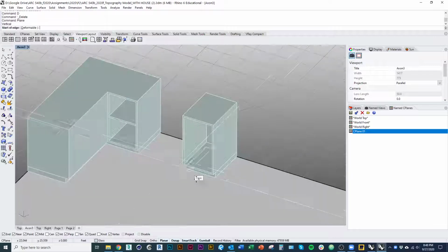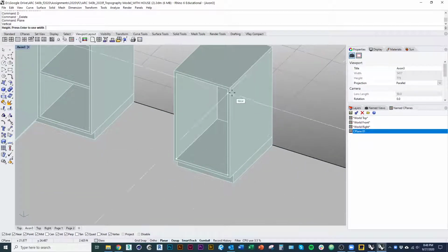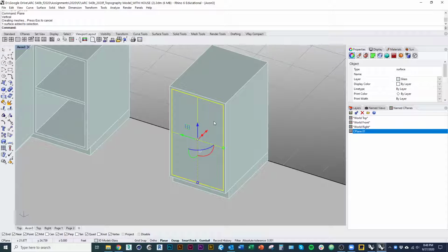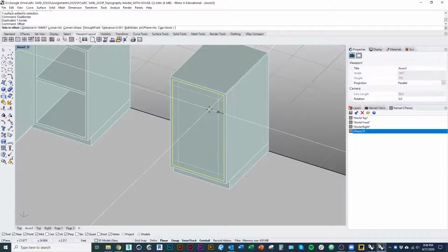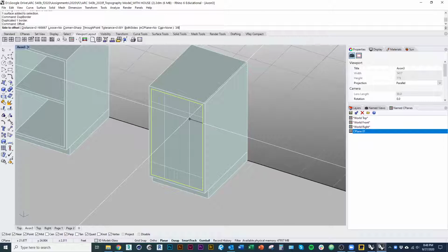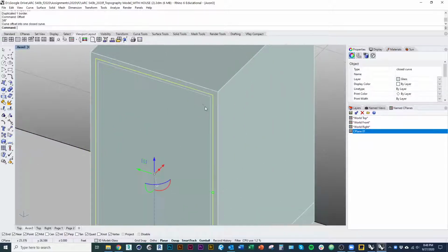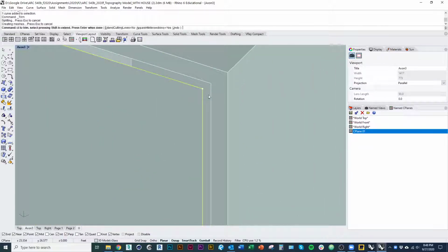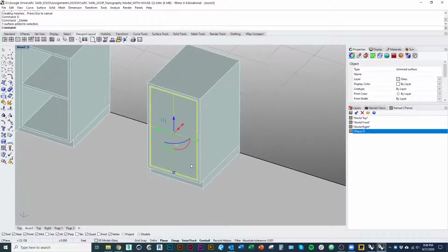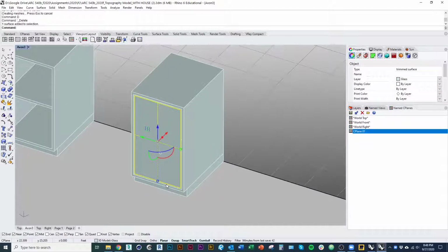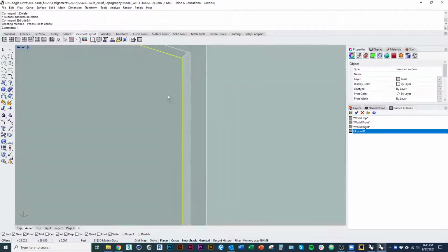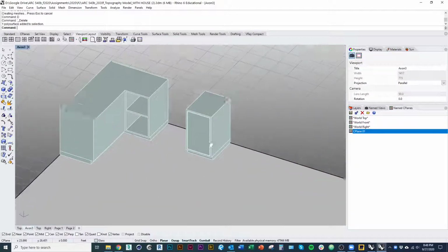And then I could do kind of the same thing. I could go vertical plane. If I were to draw a door, I guess to do that, I would go deep border, get the outline, and then offset the outline. Probably more like 3/8 or something. I'm not sure what that gap would be. Trim the gap so we have a little bit of a space between the door and the frame. And then I'm going 3/4 on that extrusion.